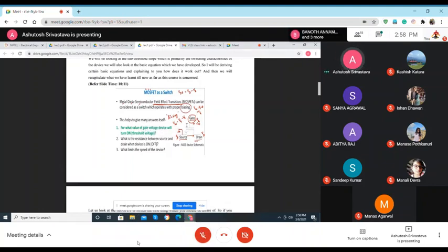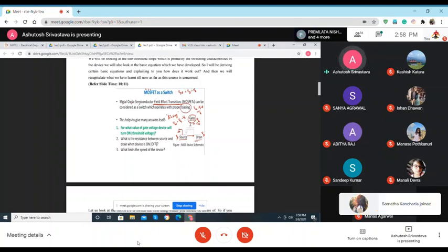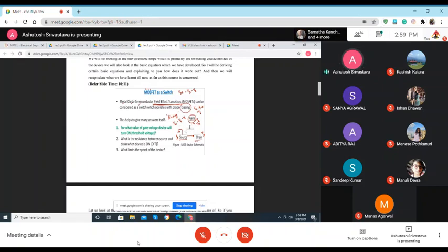That in the p type, at the oxide semiconductor interface, MOS basically means oxide insulator semiconductor interface, if at very small dimensions of a few hundreds of nanometers you are able to invert, then, if it's a p type body, what would be the majority charge carrier? Holes.